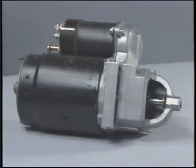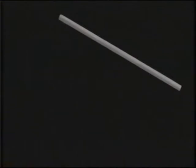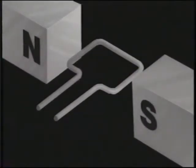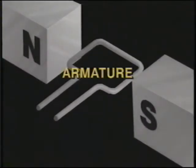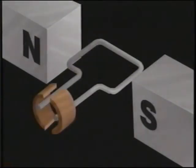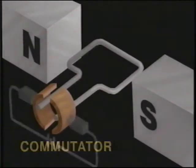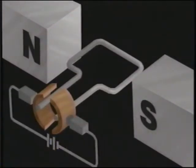An electric motor is designed to take advantage of magnetic push. The conductor inside the motor is bent into the shape of a U. It's connected to a pivoting base that allows the conductor to spin between the two magnets. This conductor is called an armature. Around the base of the armature is a split copper ring called a commutator. Outside the commutator are two brushes that slide along the commutator and provide an electrical connection for current to the armature.